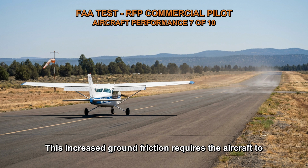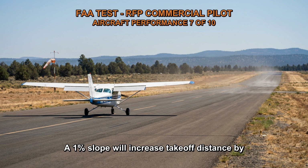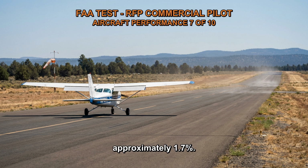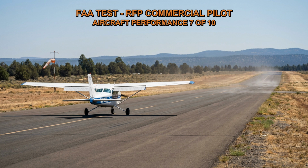This increased ground friction requires the aircraft to accelerate for a longer distance before it can reach takeoff speed. The amount of increase in takeoff distance will depend on the degree of the runway slope. A 1% slope will increase takeoff distance by approximately 1.7%. For example, a 2% uphill slope will increase takeoff distance by approximately 3.4%.